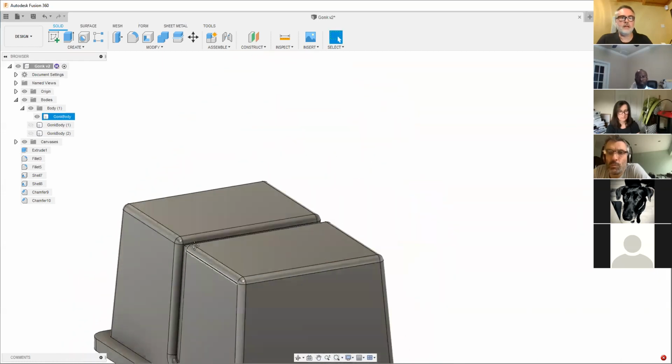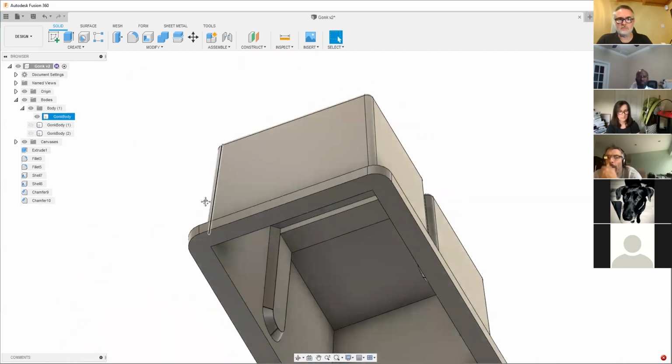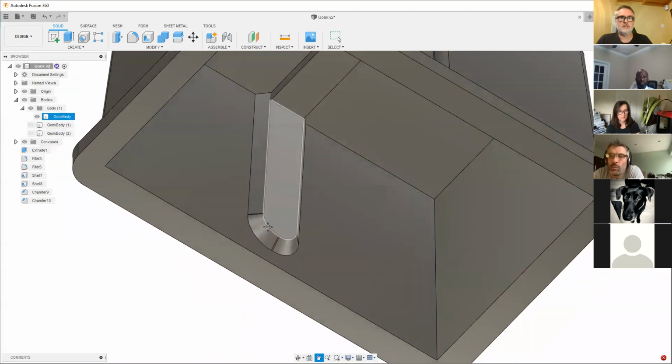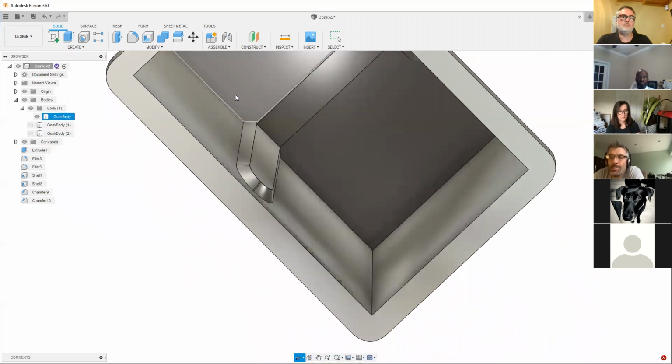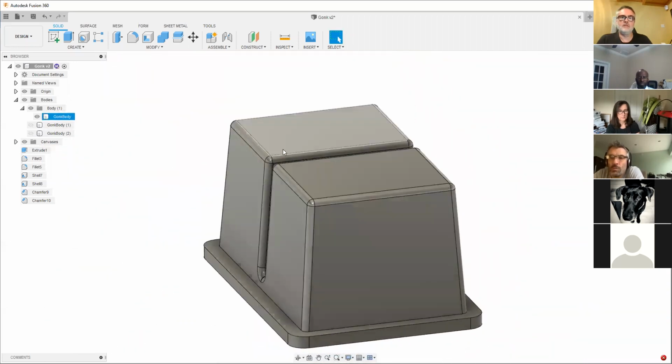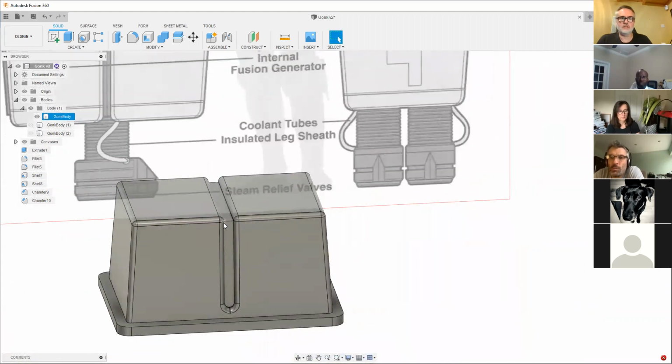So what I've done now is I've fixed this so that I know this will print. There's no overhangs. It's going to print these at 45. Once it gets up the top, it's just going to bridge. It'll bridge those. It'll be a bit messy underneath, but your top will be clean, and I'll end up with a clean print.